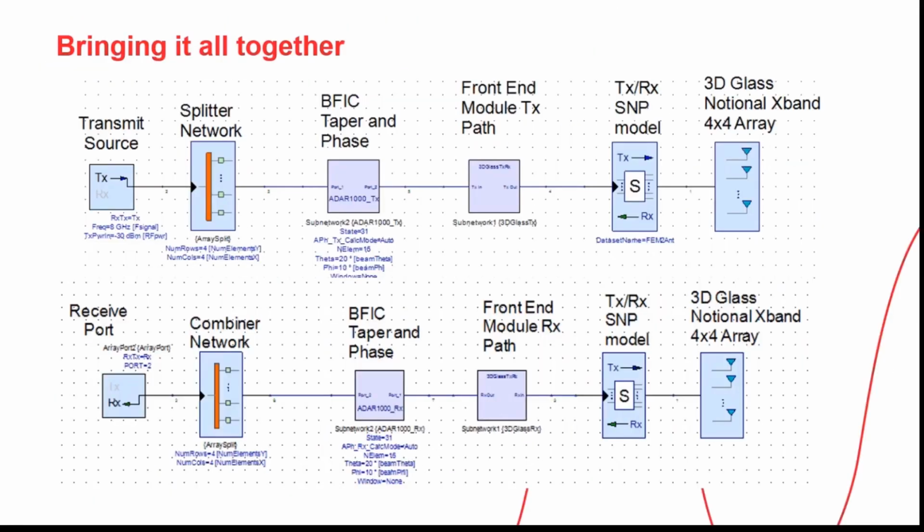So combining all of this together, it's going to let us create a transmit and receive path, which includes our phased array antenna, all of the S parameter models captured here for that, as well as the actual beam patterns. It's going to be a very accurate front-end module transmit and receive path, and then a measurement-based, highly accurate behavioral model of the beamformer IC. With all of these together, we're creating a system-level analysis of this phased array using extremely high fidelity simulation and measurement based models that come from ADS or from our Keysight test equipment.